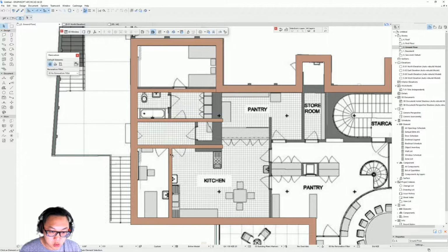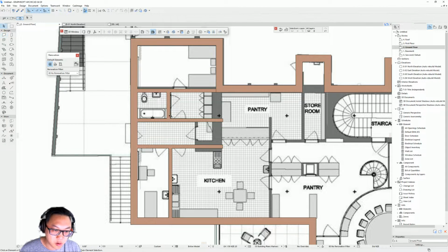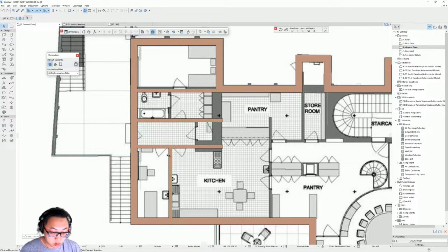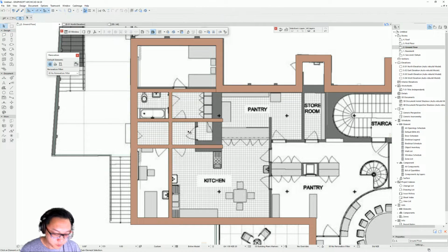And you can see that this wall here is kind of in line with this one. So instead of just copying a wall like this, or tracing another wall, the thing is that they might not be lined up, or you'll have to measure it again. So what you can do is take the wall and just drag it here. So now you know it's aligned straight. And if you press Ctrl and go over a wall, there's a scissor tool that pops up, and if you click that, it allows you to cut it, and now you get the other wall on the other side.